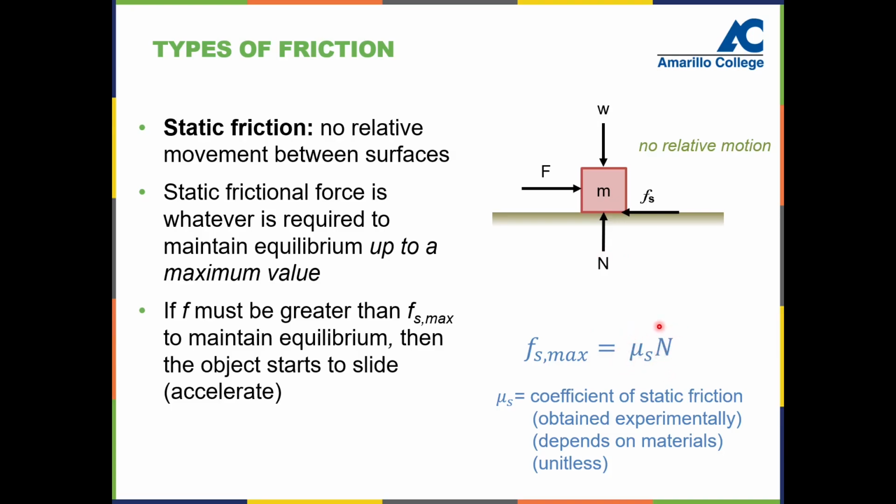So what we do here is we lump all those weird, complex things together: the difference between two materials, the roughnesses, and also the molecular interactions. They all get lumped into this kind of slush constant, which we call the coefficient of friction. Then we also have what we call the normal force, and if we multiply these two things together, that's what we come up with as the force of friction. So this is the model that we use to model friction.